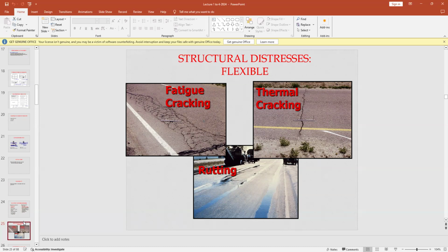Sometimes it has to do with many things. It's not only the loading, but the proper selection of the materials and what we call the matrix of material: in what proportion the material should be used, and in what manner. And I'm sorry to say, as a highway engineer, the mix has still not been optimized.